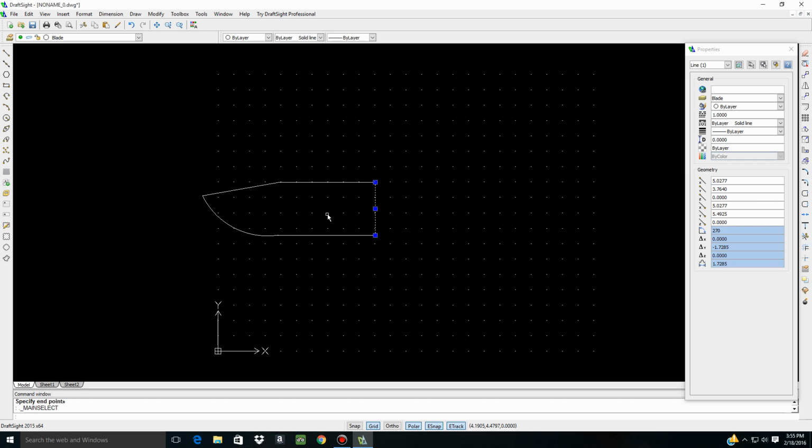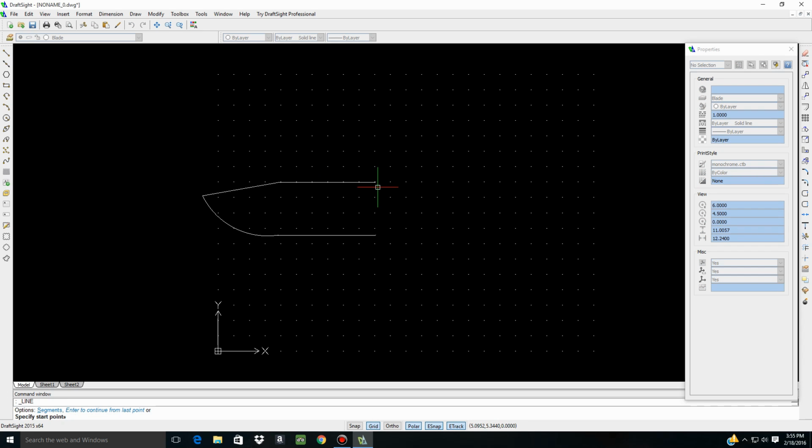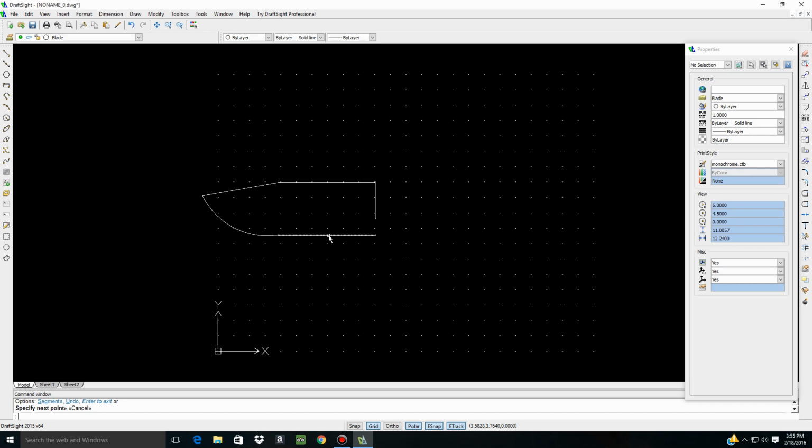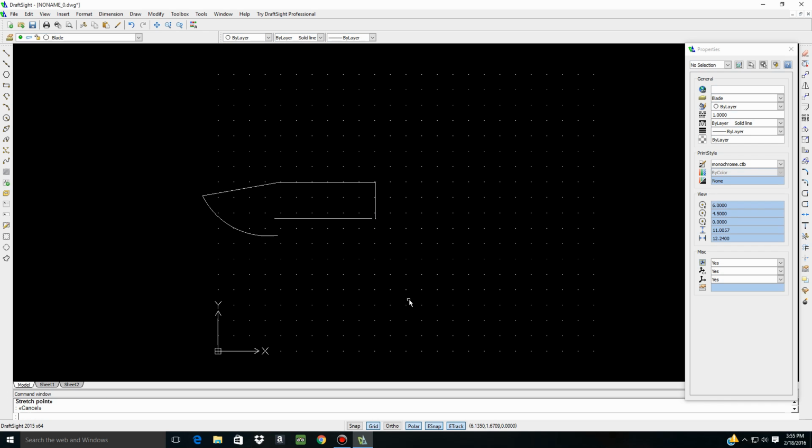So first thing I'm going to do is highlight this line, and I'm going to delete it. So go over here, hit your little eraser, and it's gone. I'm going to recreate this by selecting the line, coming down. This blade is a little too fat for my liking, and we'll cut about a half inch off of it. Now all I have to do is bring this up. Now it's not going to E-snap it for me on the end, so I'm going to go off a little bit on purpose, and I'm just going to leave it hanging out there in outer space.